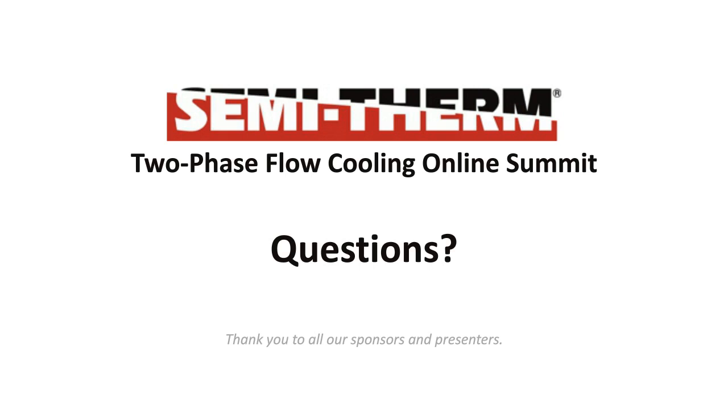Okay, we have a question about the mechanical characteristics of the foam. Is it strong enough to hold moderately high internal pressure? The short answer is yes. Metal foam has many applications beyond heat transfer, including numerous structural applications. It is used in sandwich panels, as energy absorbers for impact. Metal foam has been characterized both in compression and tension fairly well, and it has been proven in pressurized environments as well. And furthermore, the braze joint is typically not the weak point.